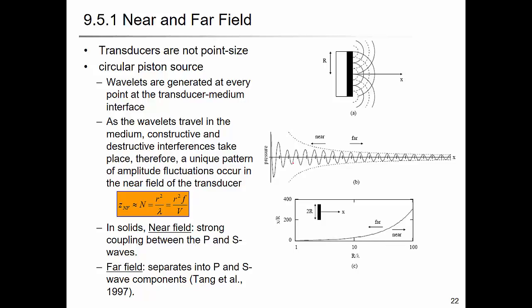At some region, you have a wave that's not P or not S or any body wave. But after a certain wavelength, it becomes the P wave or the S wave. Right? So it needs some distance to be able to form a body wave. And that range is called the near field. And the near field can be calculated using this equation.